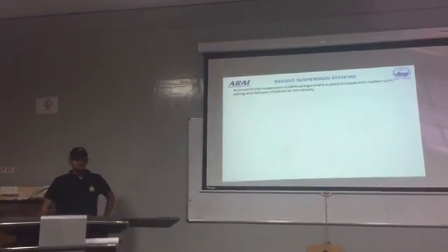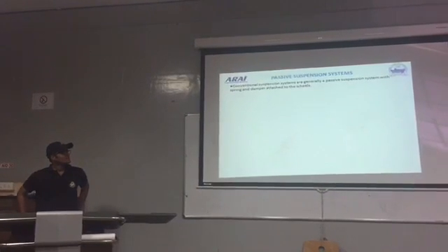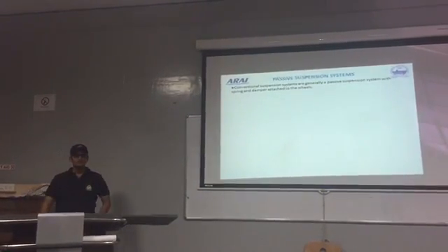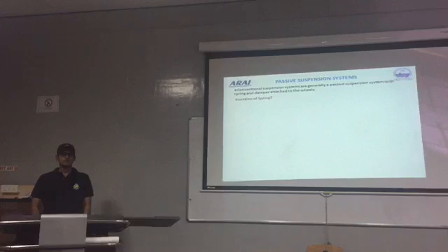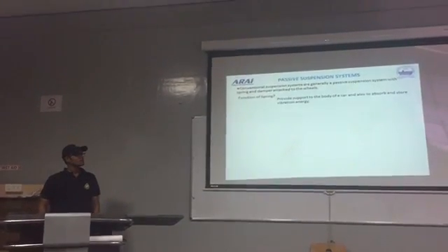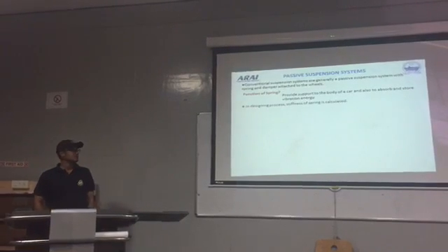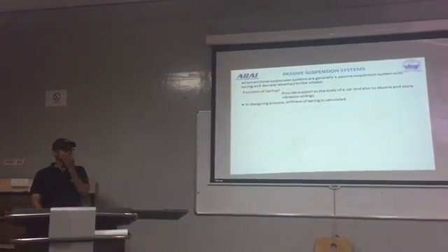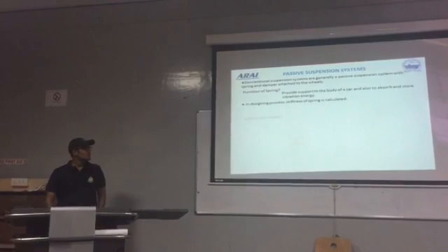So what is a passive suspension system? It contains a spring and a damper attached to the wheels. What is the function of the spring? As everyone knows, it provides support to the body of the car and also absorbs and stores vibration energy. In the design process, the stiffness of the spring is calculated.